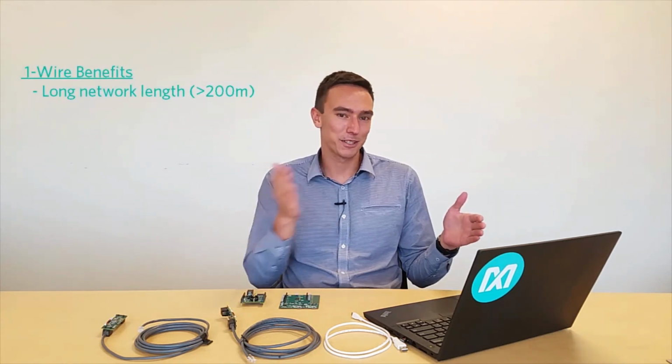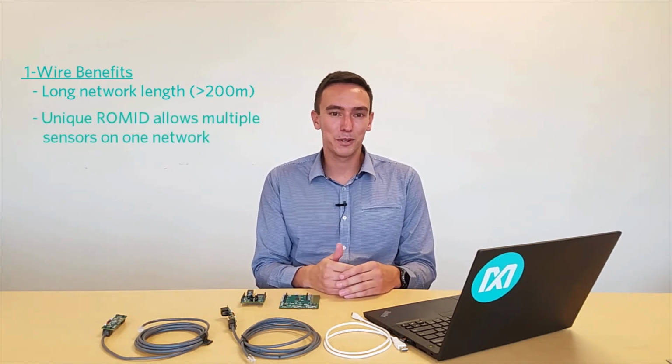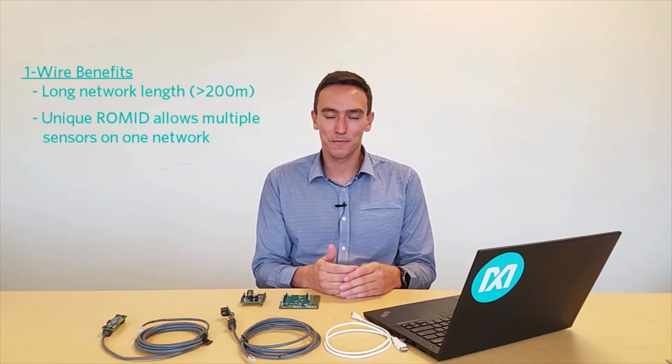One of the advantages of the one-wire protocol is that it can operate up to several hundred meters in length, whereas I2C is limited to about a meter. Another advantage is that each device has a unique ROM ID, allowing for multiple of the same device type on a single network. However, in one of these multi-device networks, there's no way to tell where each device is physically